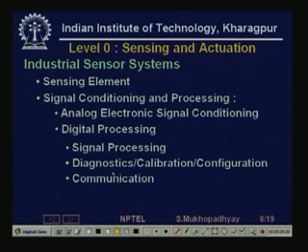Fine. So that is diagnostics. Sometimes sensor characteristics degrade. For example, suppose a sensor develops a bias. You can have algorithms to actually detect the bias, and you can do its own calibration. A sensor can send information that it has developed a bias, or the sensor can be interrogated, and you can find that it has developed a bias. So, its readings will be interpreted accordingly for greater accuracy.